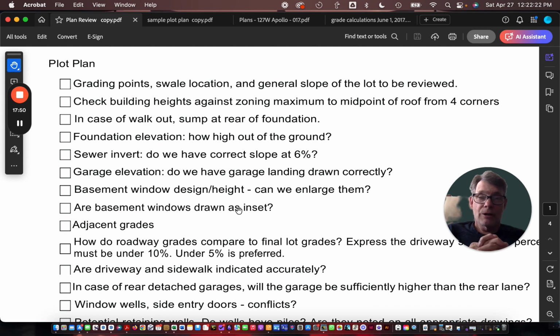A far better way to do it is, because the concrete basement walls are thick, you've got a big thick opening there, set the basement window inside, inset into the concrete wall. Now it's partly covered, and you'll have a much better time waterproofing that detail.